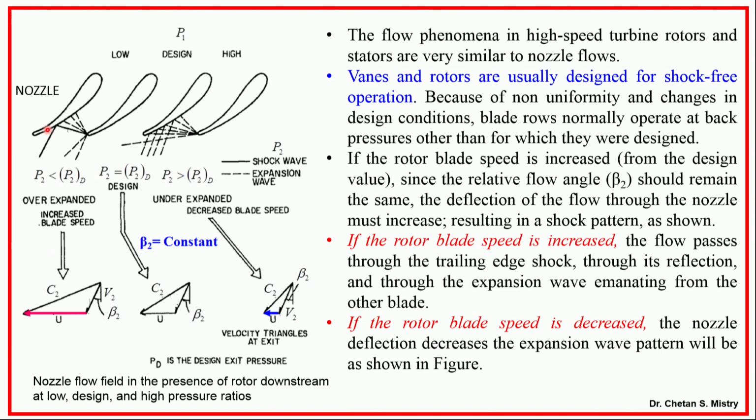So, under that condition, when my rotational speed is higher, and this rotational speed changes as per my requirement, because I have a flight envelope: takeoff condition, cruise condition, landing condition. Suppose I am talking about a military aircraft, I need to do a lot of maneuvers. So, in all these conditions my rotational speed will be changing as per my thrust requirement. So, my flow physics near the trailing edge is changing.